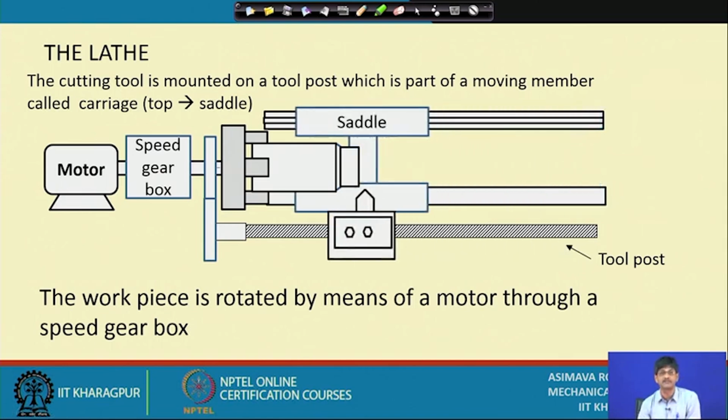The carriage can travel from one side to the other, just like a train on rails. It has one straight rail on one side, to provide enough bearing surface. A flat surface is the best bearing surface, and on this side, in order to keep it located in a particular direction, we have a V-shaped guide.